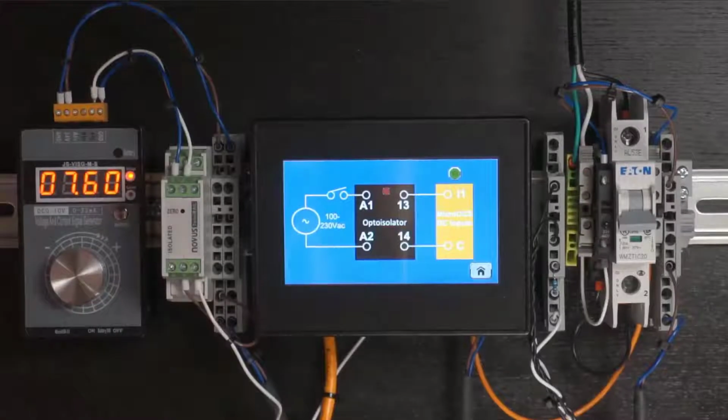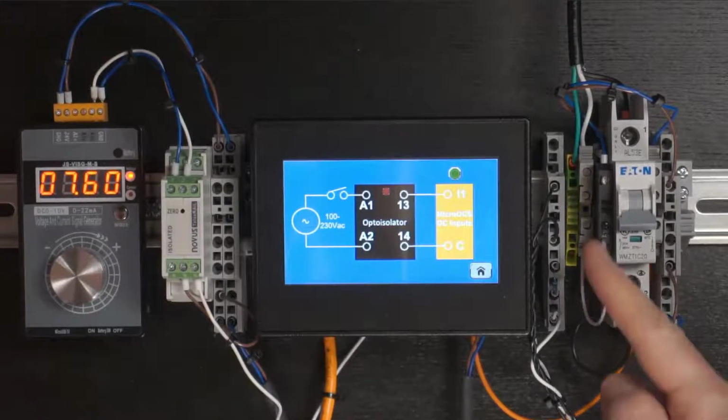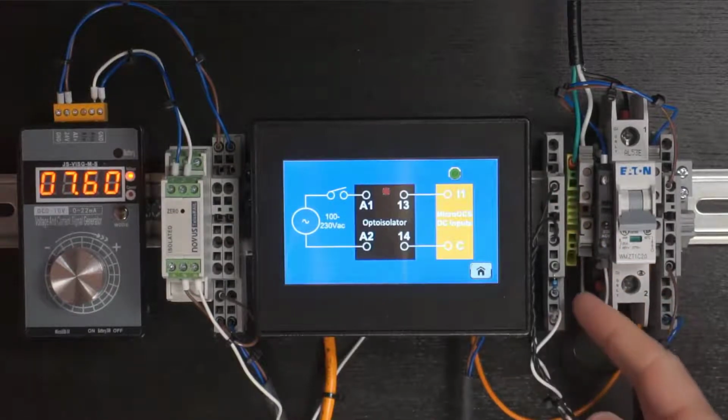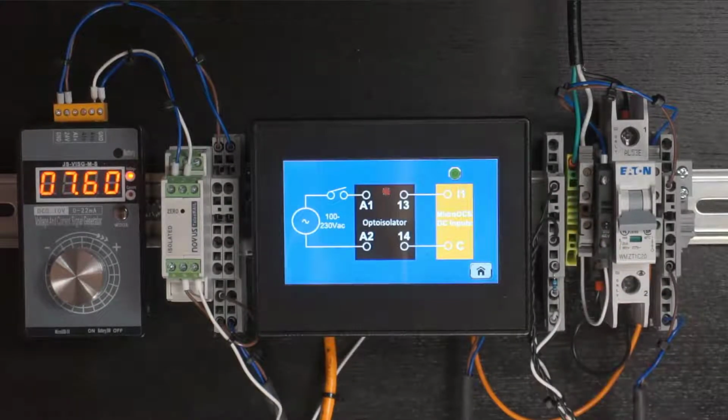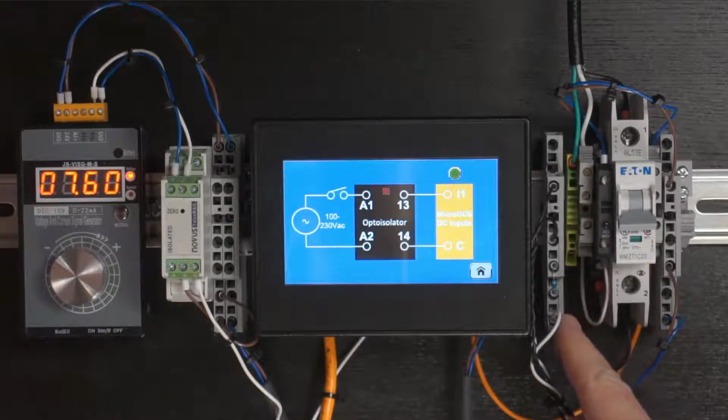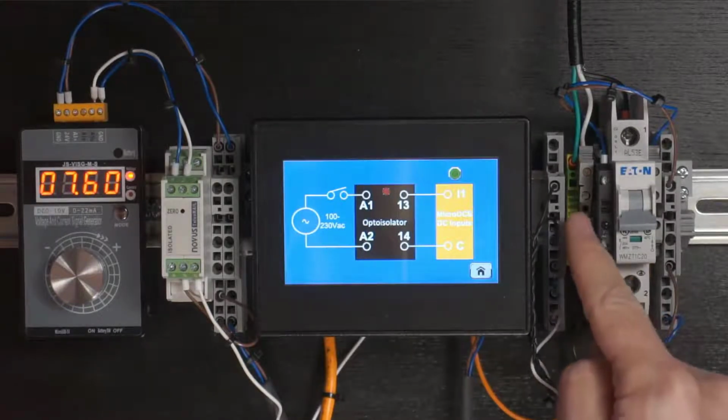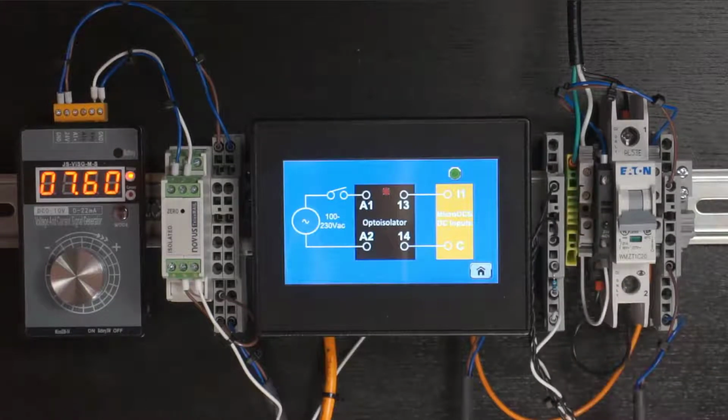Let's go back here to our bench setup. I'm just simulating an RTD here with a resistor. I've got a 150 ohm resistor, and 150 ohms is right in the range between -50 and +200 C. I've got that connected with some leads, one lead on one side and then 2 leads on the other side, like a three lead RTD. Those are wired directly into, I think, one of the analog inputs of the Micro OCS.